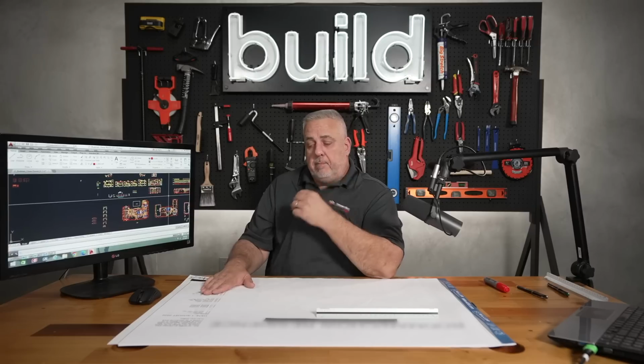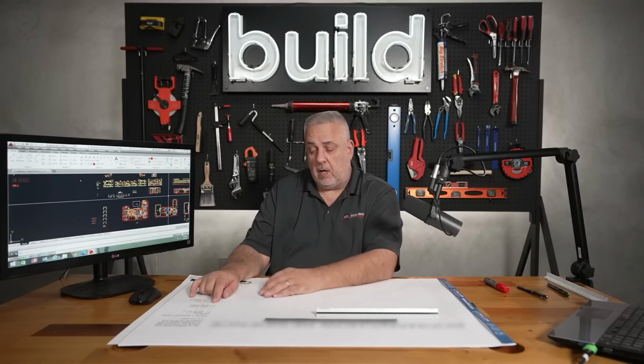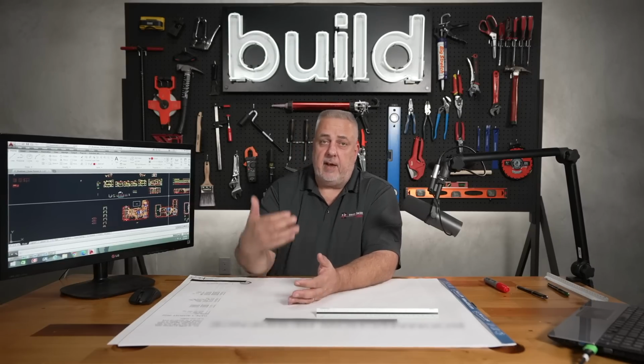Now, why would I do that in this kind of series of 10? Well, as we develop this drawing, if for some reason we make some changes and we need to develop another building elevation sheet, well, if we have them sequentially numbered and the building elevations are sheets A12, 13, and A14, and the drawing set goes up to A30, and I insert it, then I have to go through and change all the numbers of the subsequent drawings all the time. Ask me how I know, right? 30 years of experience will help you develop some little tidbits of things to dodge some of those problems.